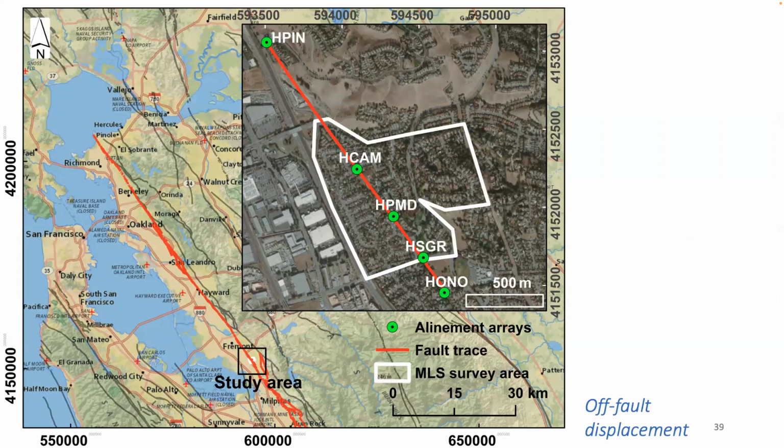In this area along the Hayward fault, so again, this is the San Andreas fault, which kind of runs through San Francisco, this is the Hayward fault that runs right down through Oakland and actually right through the UC Berkeley campus as well. The USGS has been monitoring the Hayward fault since the 70s. They have these stations set up along the fault where they basically go out once a year and measure deflection angles with a theodolite. And they are able to determine from those deflection angles, because they're using a 1 second theodolite, down to the kind of millimeter level with some good observational techniques.